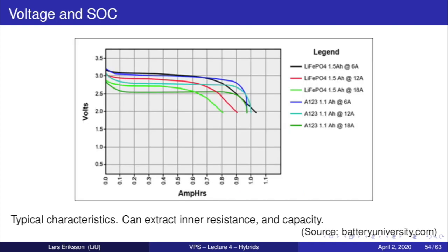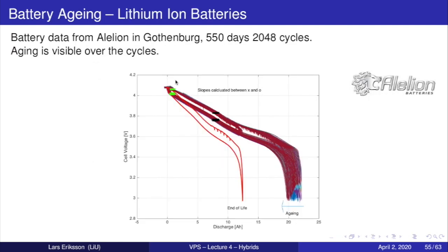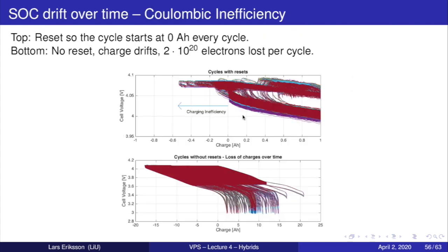When it comes to estimating the state of charge, we have 2 challenges. One is that the voltage curve can be flat, and the other is seen in the coming slide. In the next slide I will extend this part of the plot where we'll look specifically at what's happening here when we start to charge and when we come back again. So we had 2 challenges with the state of charge. One was that it might not be easy to detect the voltage change. This chemistry is easier, but the other chemistry was more difficult.